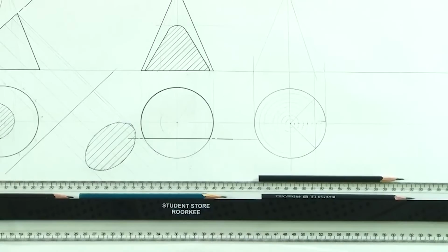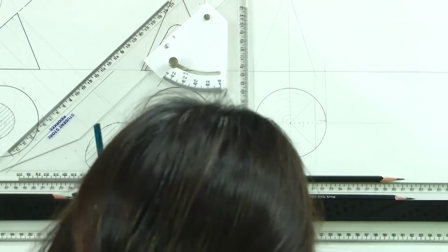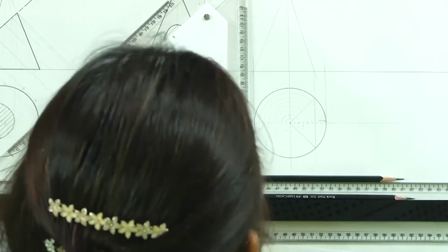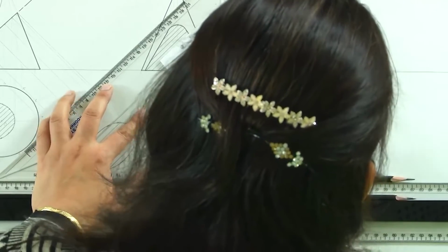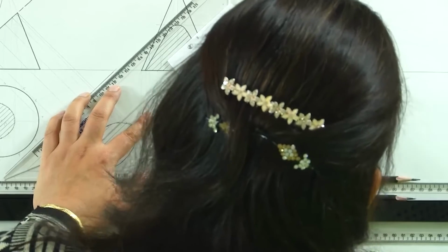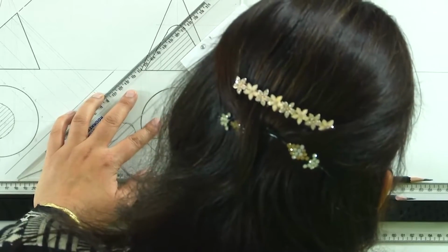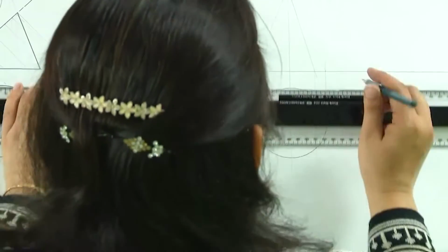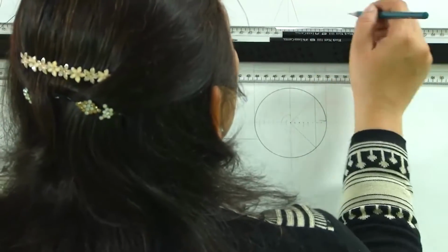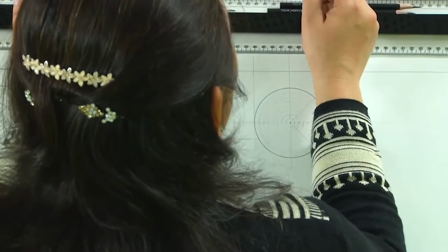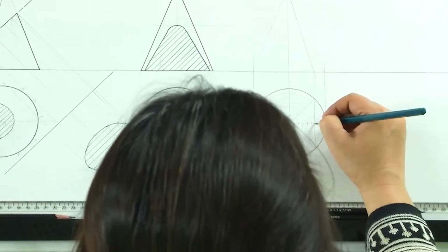Now, as we remember the concept that each of these concentric circles represents a circle parallel to the base. So, what we are doing? We are going to take these projections up, and it is on this generator that each of the circles is going to pass, and that is where a plane parallel to the base plane will be passing. So, I will now draw these horizontal planes represented by these horizontal lines. So, these are the horizontal planes which are now intersecting in this.